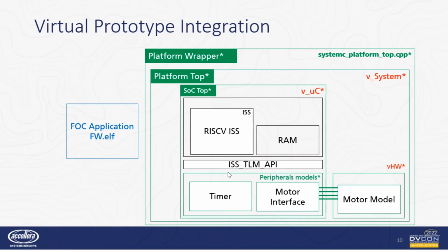Taking advantage of the SystemC nature based on C++, the simulation runs based on the model executable and calls the firmware application as an executable argument. This executable is refined taking advantage of the framework previously described.